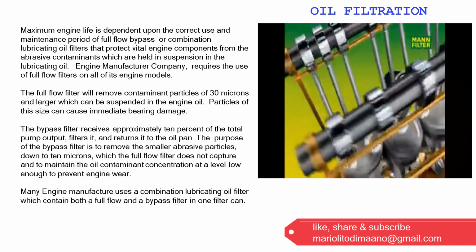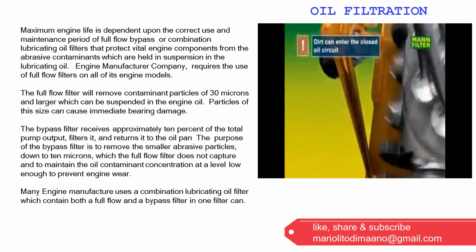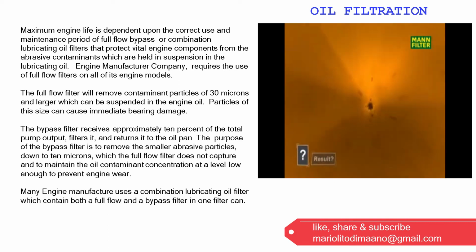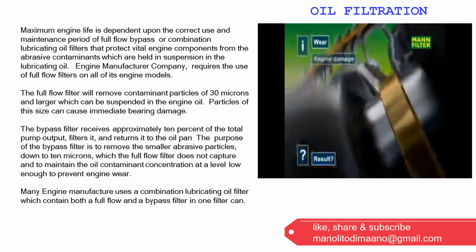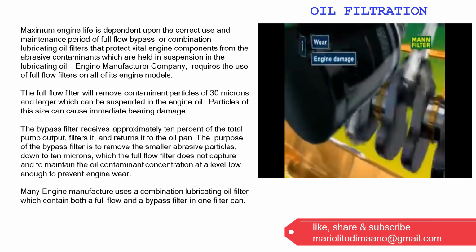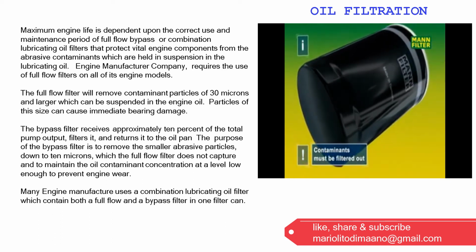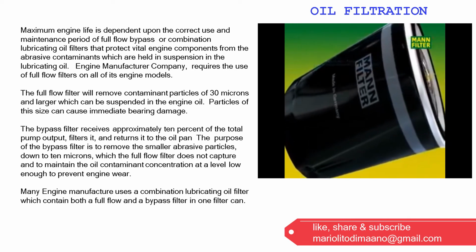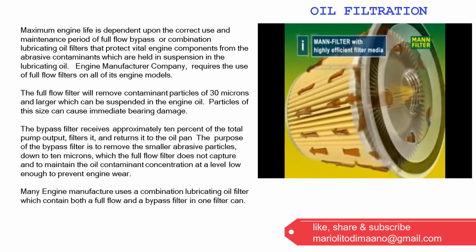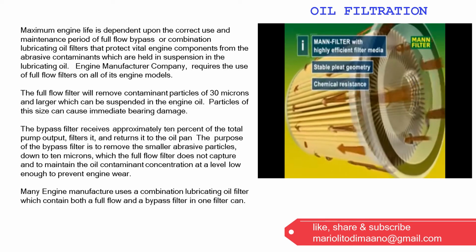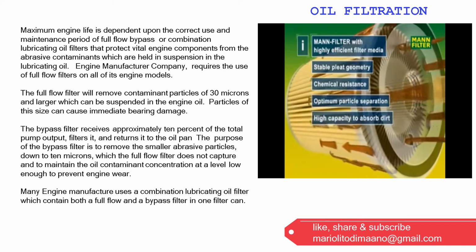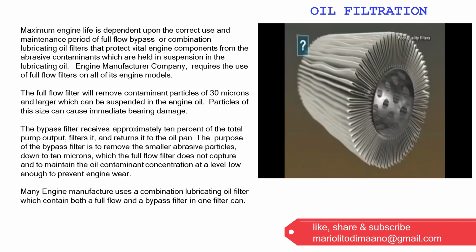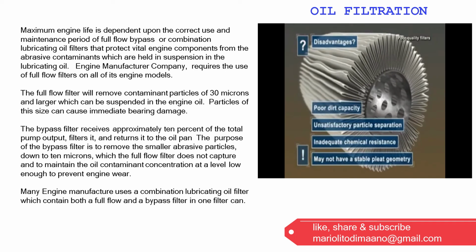The service life of a combustion engine will be enhanced through the use of quality engine oil and filters. As the oil circuit becomes contaminated by combustion residues, metal and other dirt particles, it's absolutely essential to use a reliable filter to clean the oil. One frequently used type is the spin-on filter. The dirty oil is pumped to the filter, where it passes through a special filter medium with pleats designed to withstand high-pressure differentials and which is resistant to aggressive chemical substances in the oil.